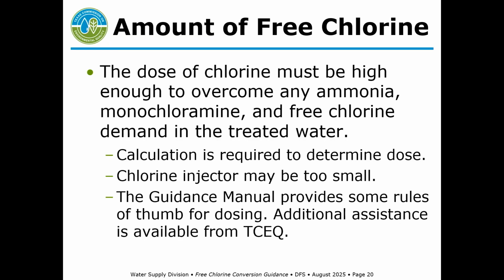What's the amount of free chlorine you need? The dose has to be high enough to overcome any ammonia, monochloramine, and free chlorine demand in the treated water. You've got to do some calculations, and you may find your chlorine injection system is too small. And as I mentioned, you can get some help from the guidance manual. But I guess the real point I'm trying to make is recognize the limitations of your existing chlorine feed equipment.